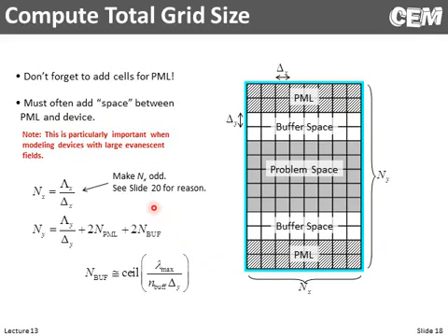So putting all this together, what does this look like? We have the size of the device in the X direction, or the horizontal direction. We will divide that by the grid spacing, and normally what we do is we round that up and we figure out how many cells wide the grid is. And we'll see when we get to the code a little bit better how that is handled. But the other thing I want to mention is that we always want to make this number odd.